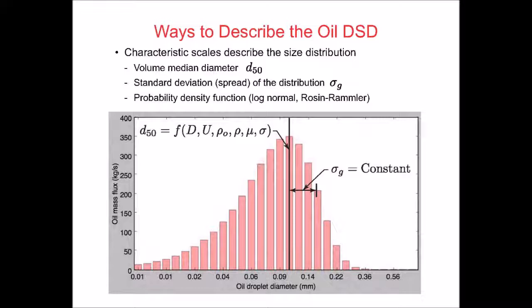So here we can see the effect of flow rate. If I increase the flow rate, so I have a higher exit velocity, I'll get smaller droplets. So the dark ones have a higher exit velocity, smaller droplets than the larger ones. Droplet size is on the x-axis. If I change the, let's see, volume.